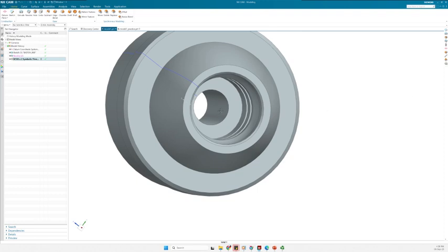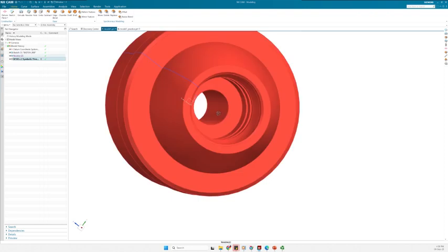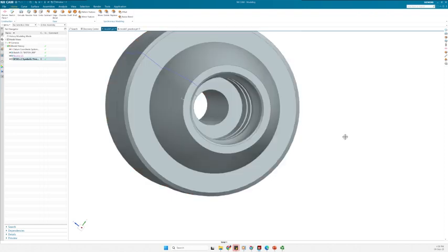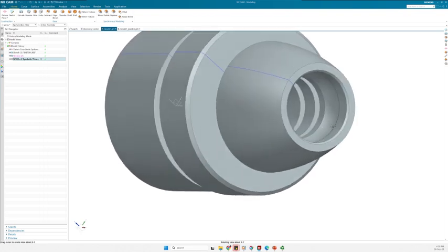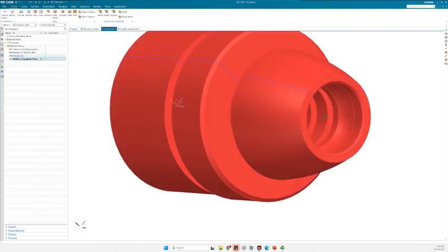Then depending on the diameter, we can decide about having interpass, or first making a smaller drill and then making a bigger drill to finally reach our desired diameter, or directly making the final drill after the spot drill. So internally we have two grooves here.